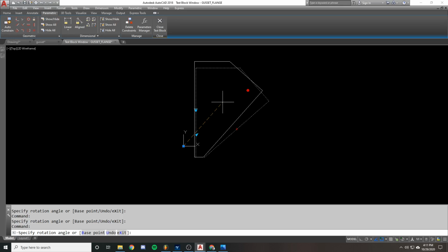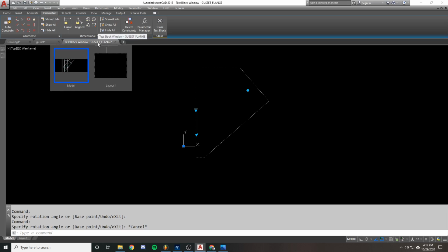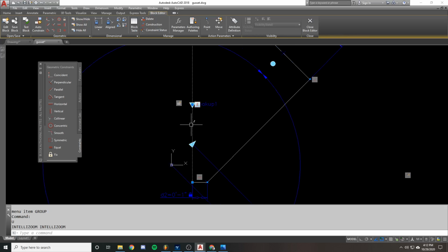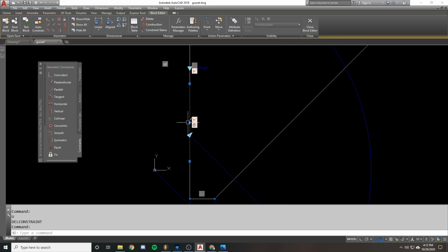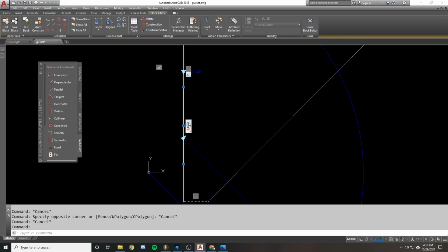So I thought to myself, how can I make this work? Well, I went through a lot of permutations on this thing, trying to figure out how I was going to get it to work. And my solution was to take a line on top of this one, a short line that overlaps it, fix that line so that it cannot move left or right, and make it kind of short, because that way it never sticks out. And then make it collinear.